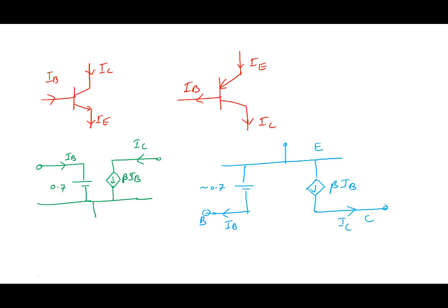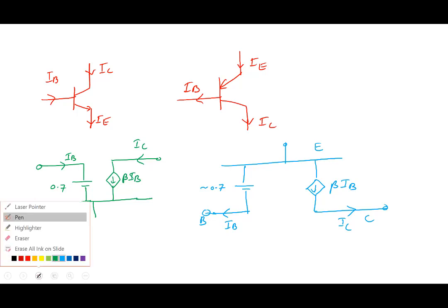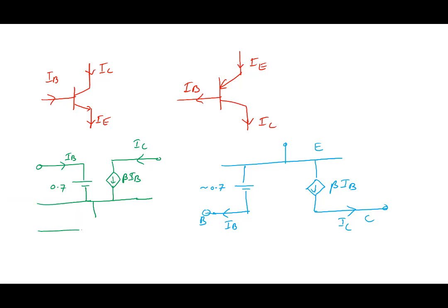This one in small signal, without drawing the small signal, this became R pi, this became GM V pi. For simplicity, without going into too much detail, this was IB, this was IC. I'm not putting R naught and all that. This is how the small signal became.